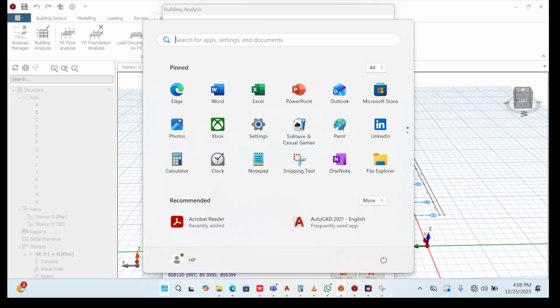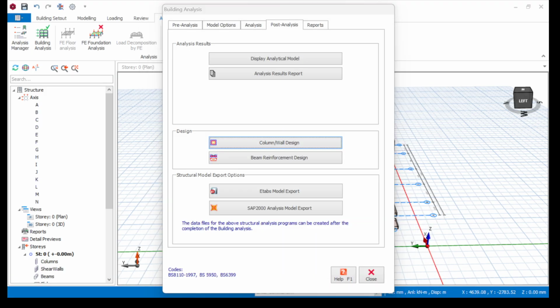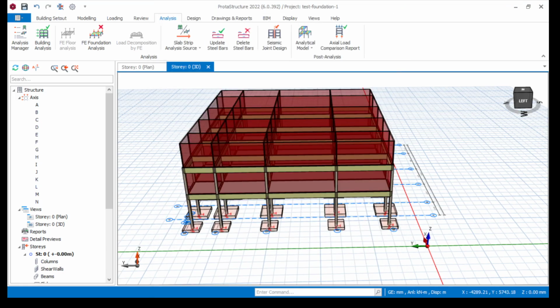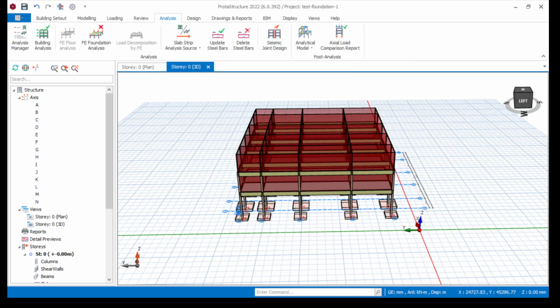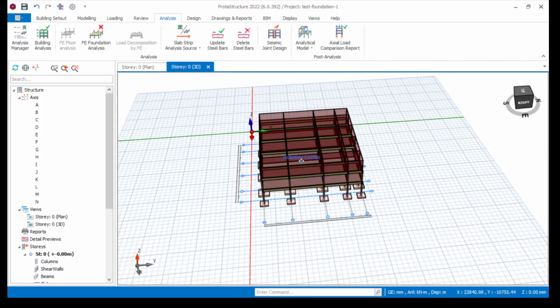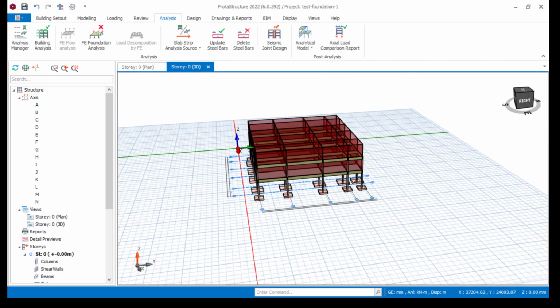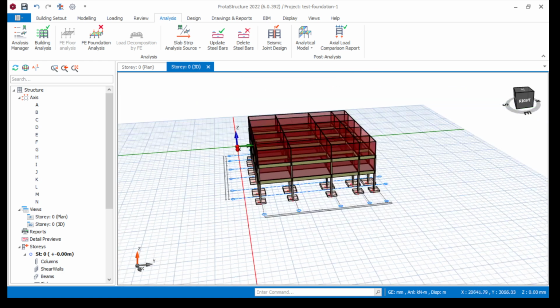So we can close this. Why are the rest 4Y16? You need to be very, very careful. In fact, column detail is by far the most important aspect, because once you miss anything, you've actually missed it. You might just go and give a column that is having 4Y25, you go and put 4Y16 there. So you need to be very, very careful, and you need to be very, very focused.